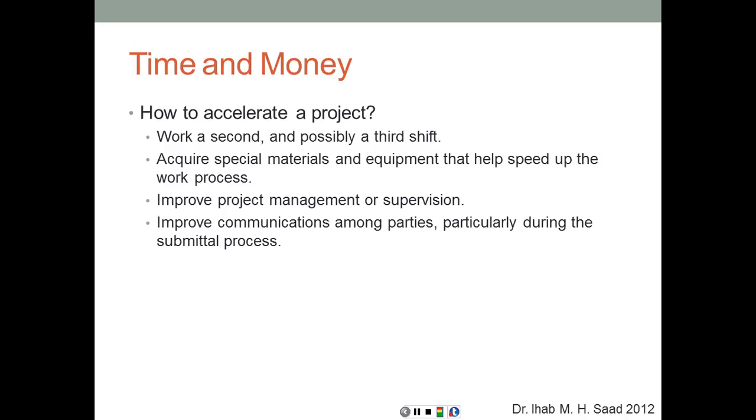Acquire special materials and equipment that can help speed up the work process. For example, in concrete, we can have accelerators that are going to accelerate the setting of the concrete so that we can remove the formwork faster. Therefore, we can proceed to the next floor faster. Improve project management or supervision. Again, project management and encouragement and so on. Proper supervision can provide better productivity rates.